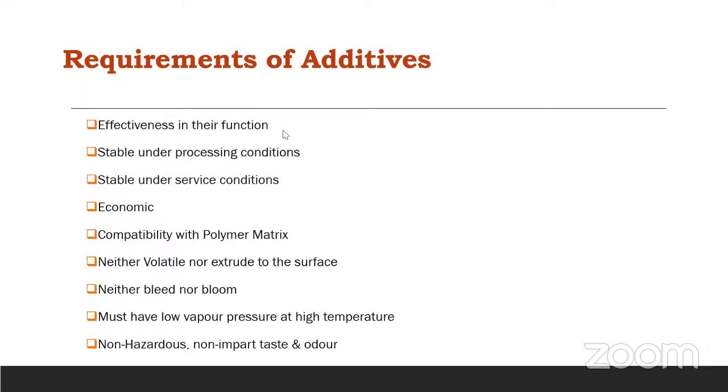But will it not spoil the strength of our parent material? No, in fact, it can increase the strength of your parent material. It will not deteriorate the strength of the material. So what happens at this formulation level? You add different materials on the basis of PHR, parts per 100 resin of material, or we can say in weight percent also. As I have mentioned, if you are preparing a 100 kgs batch, you will be adding 2%, 3%, 5% of additives, and accordingly your batch will be adjusted.